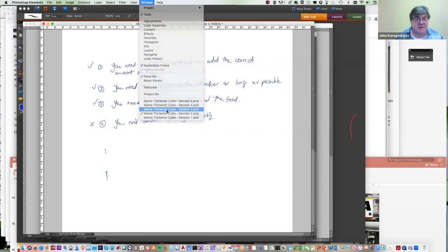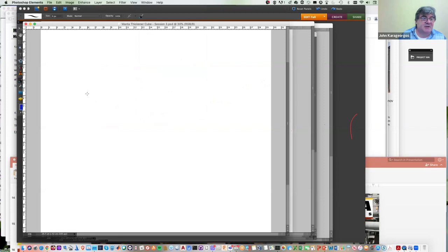Number 3: you can all get a measuring cylinder, go to your thickener feed well, get a sample, and put it in the measuring cylinder, fill it up, and you'll have lots of particles trying to settle, right? Give it a mix, put your hand on the measuring cylinder, fill it up with feed, swish it up, mix it up, and just watch it settle.